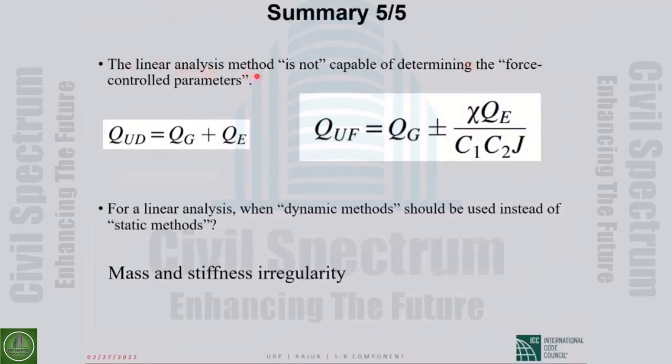The linear analysis method is not capable of determining the force control parameters. Why? It has two deficiencies. One, because we increase the base shear to have the correct displacement. By increasing the base shear, we increase all the force control parameters too. So their value is not correct.